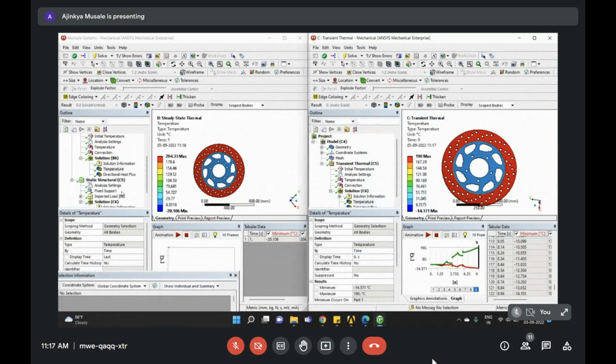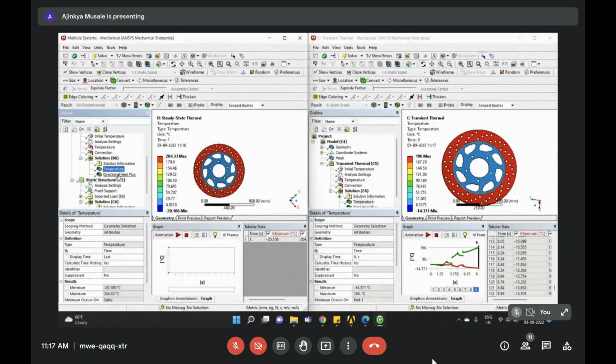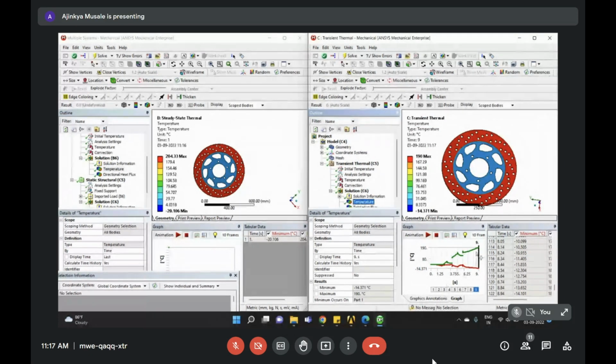But you can see over here, in results you cannot see any graphical results or anything. Here, if you go on temperature, you will have such a graph from where you can right click and say retry, and you can extract those results. Or you can do the same thing from here. You can click on this table row, right click and retry. You can get those results. Fine. So that is the main difference between these two calculations. Let's move now to our next problem for today.